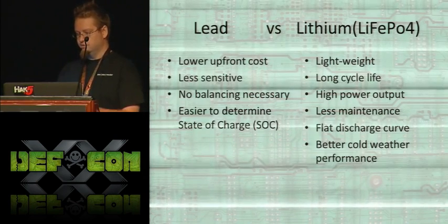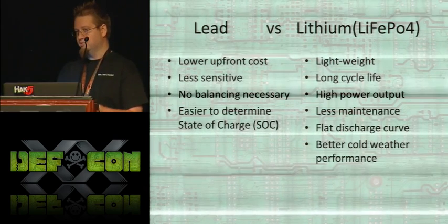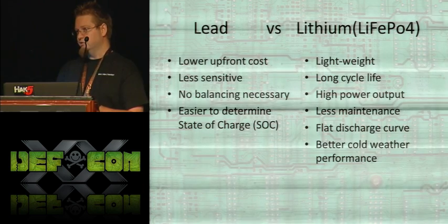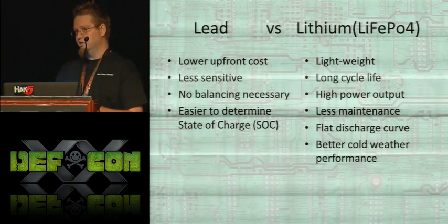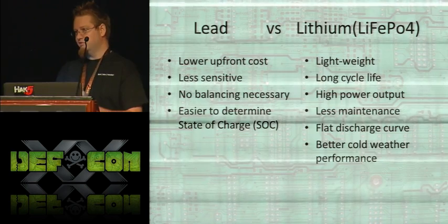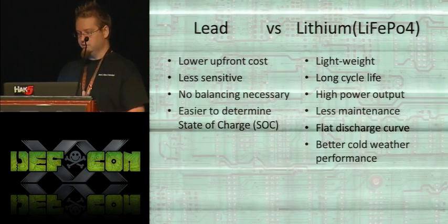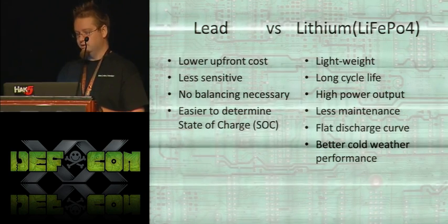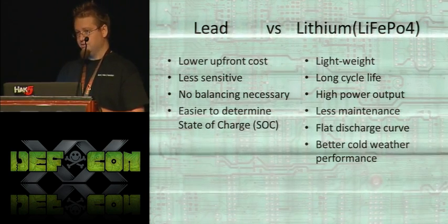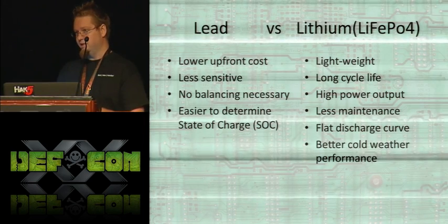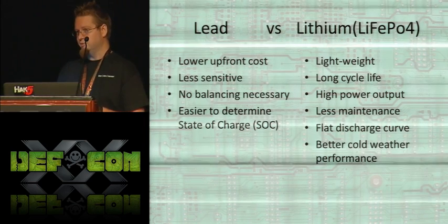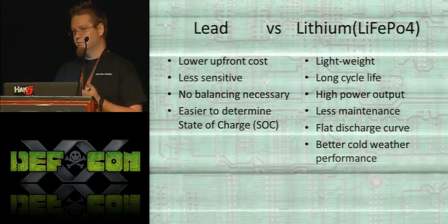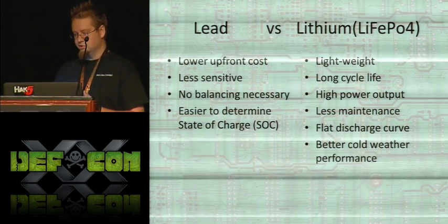So your lead versus lithium, obviously lead is cheaper up front. They're less sensitive because a flooded lead battery, you can't overcharge. All it does is turn into a fuel cell once it's full. So it just gases, and all you have to do is add water to it, and it's okay. Whereas a lithium battery, if you overcharge it, you'll vent it, which destroys the battery. There's no balancing necessary with lead because it self-balances at the top, whereas with lithium, you have to make sure all your batteries are at the exact same capacity. Otherwise, one of them will go over before others get fully charged.